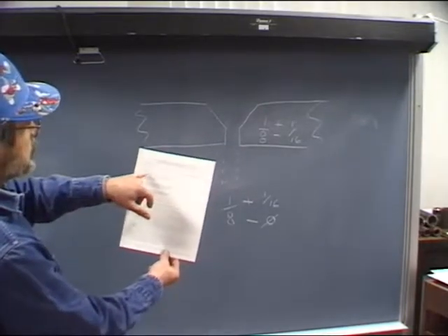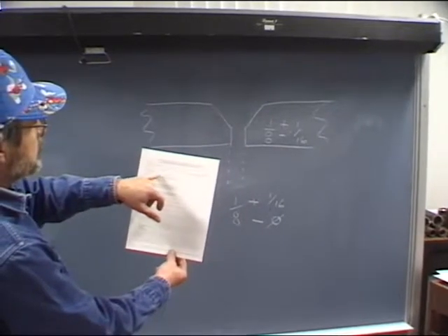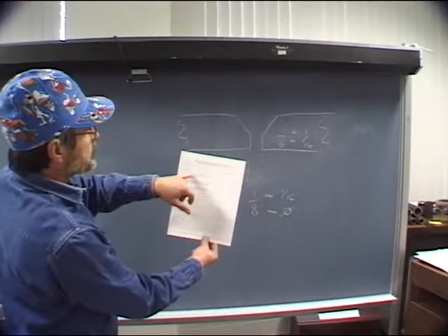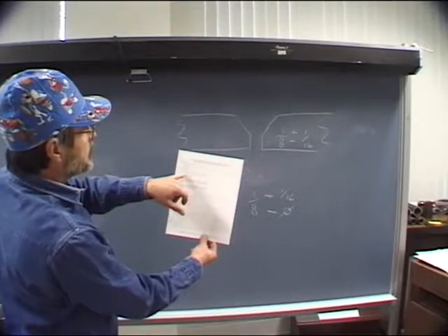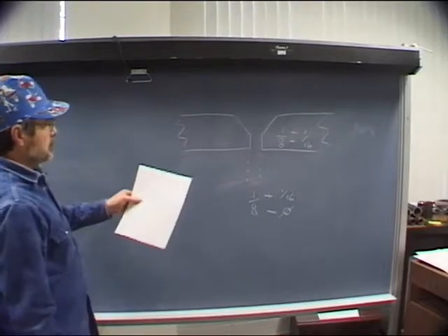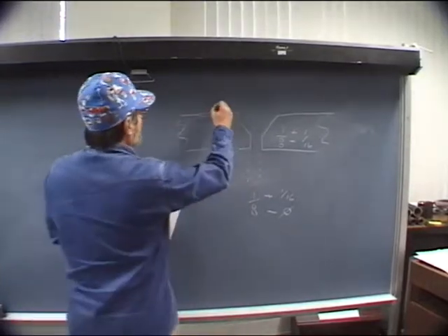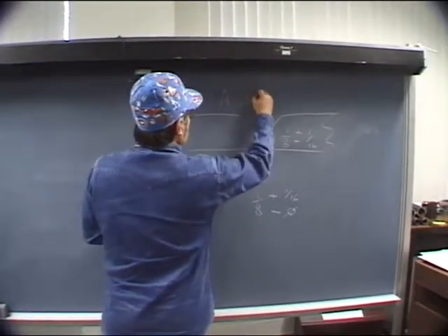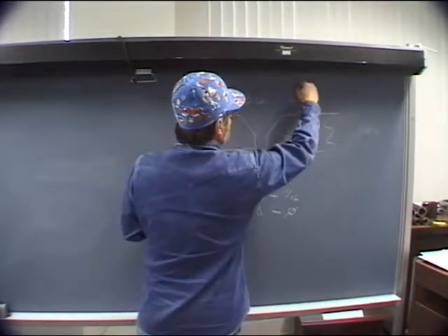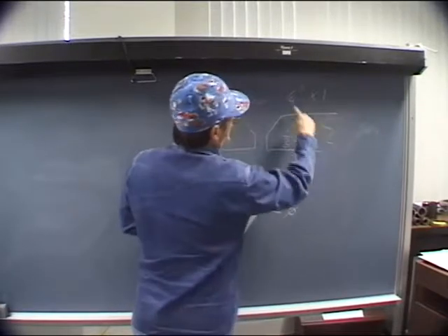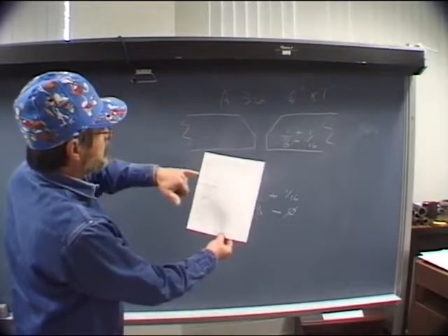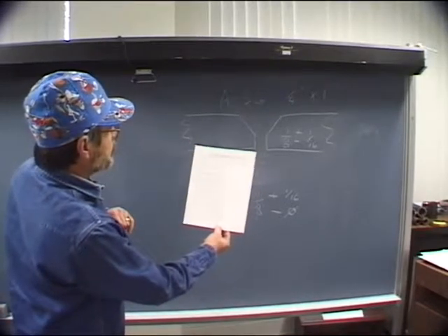And then it says joints, joint design, and we would write in single V groove. Now if we used a backing, we would have to say yes or no that we've used backing. And if we did use backing, then we would have to put what type of backing. A mild steel would be A36. Okay, A36 would be a typical backing, and you would have to put, well, what size? Okay, well, 1/4 by 1 inch thick backing, and that would be written in there, and you would have to go ahead and mark where it says metal.